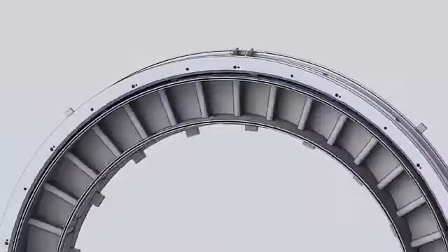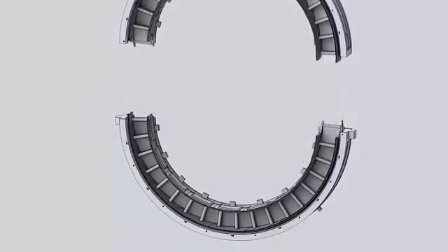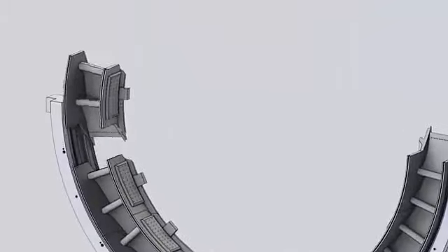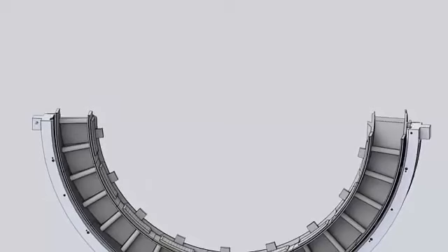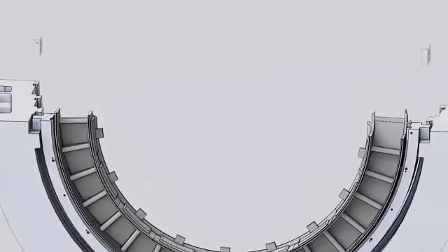The 18 segments are contained on a horizontally split retaining ring. The retaining ring is supported to the lower turbine shell by two lugs extruding from the lower retaining ring half and held in place by clamps.